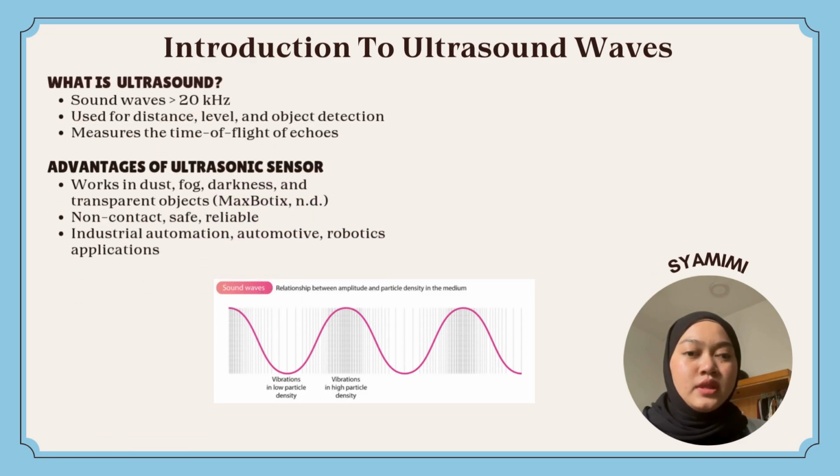Ultrasound refers to sound wave with frequencies above 20 kHz, which is higher than what humans can hear, Urata 2021. These sensors work by emitting ultrasonic sound wave and detecting the echoes that return after bouncing off objects. By calculating the time it takes for the sound to return, a method called time of flight or TOF, the sensors can measure distance accurately.